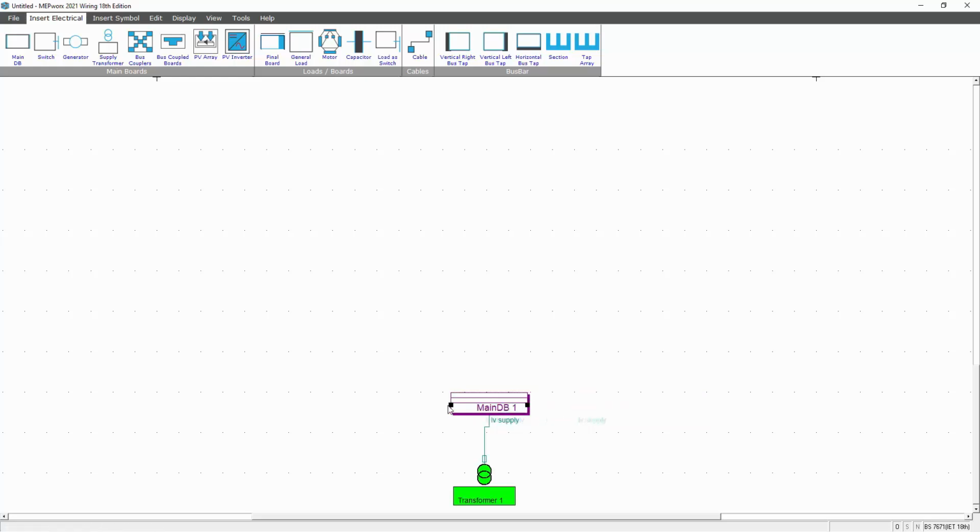And this feature comes in quite handy when you're wanting to print out from final boards, because as you build your board up, you'll find that the circuits become all squashed in on the existing default board size. So it's always best to go in and stretch it when you come out, so that when you do a printout, you can see all those ways on the board.